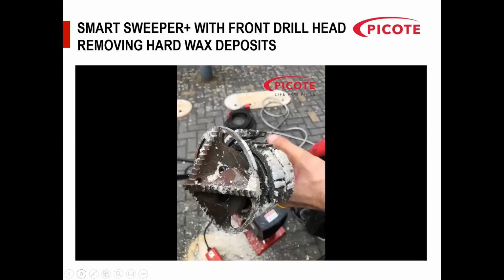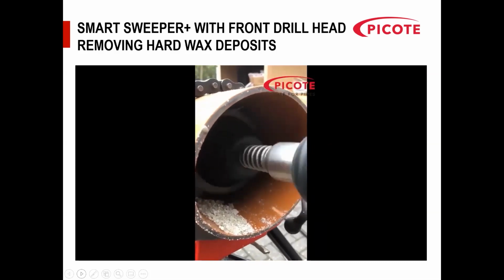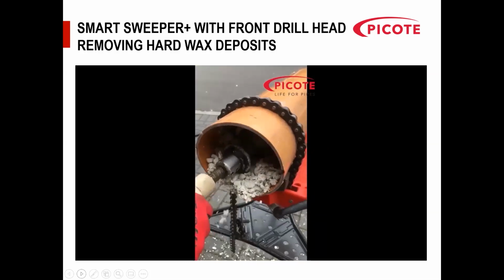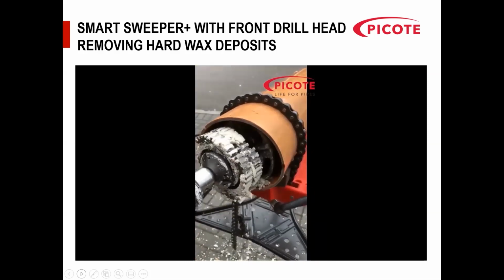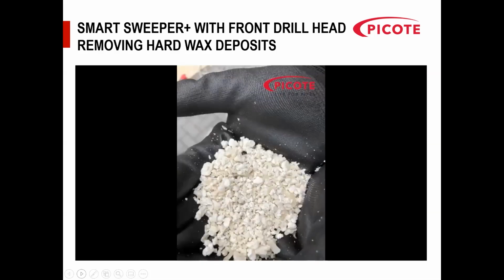So a little clip here. This is a job we worked on for a client, where they were looking to remove a hard wax deposit from inside the pipe. As you can see here, we've got the sweeper with the front drill head on. This is with the Power Plus, and as we're pushing it through and putting pressure on, it's cutting through, and the wax is coming out in little chips. This was on a 6-inch pipe, and we did the test work for the contract. You can see the size of the little pellets it was cutting it into.